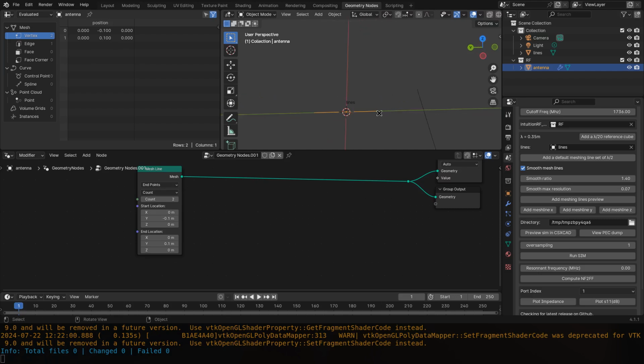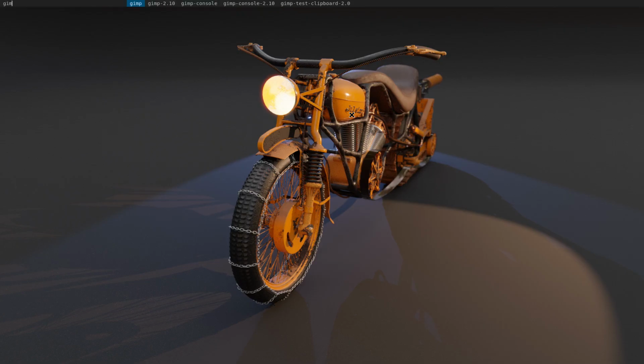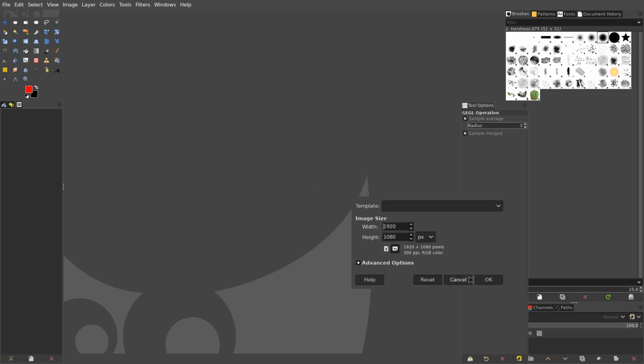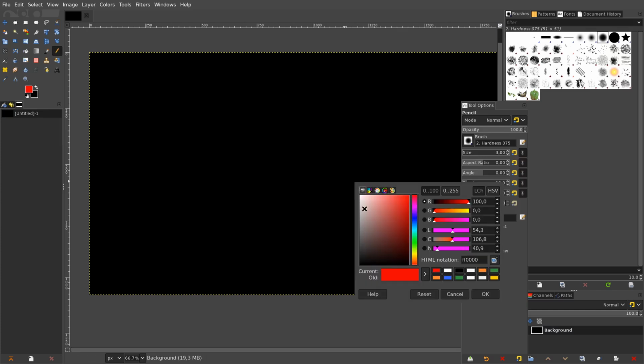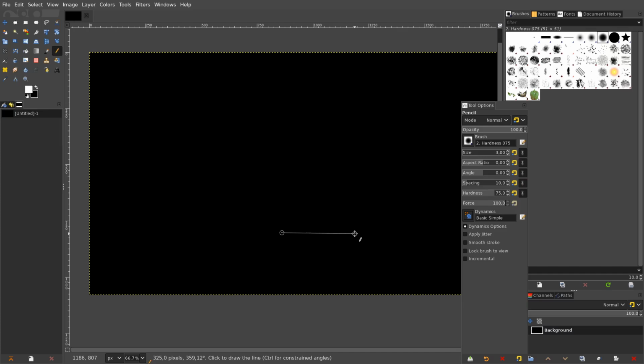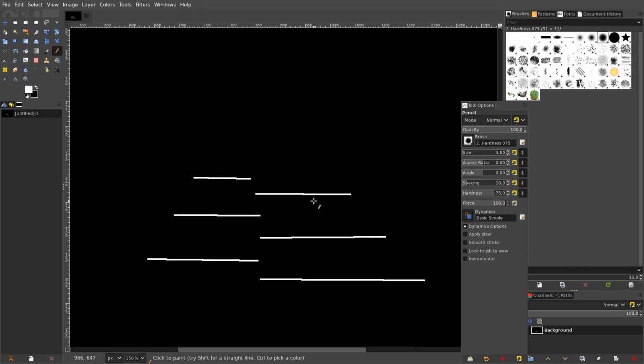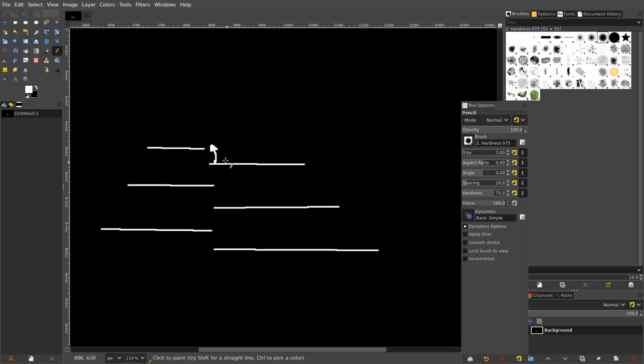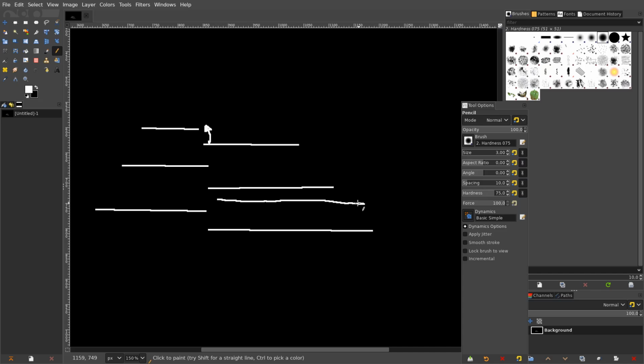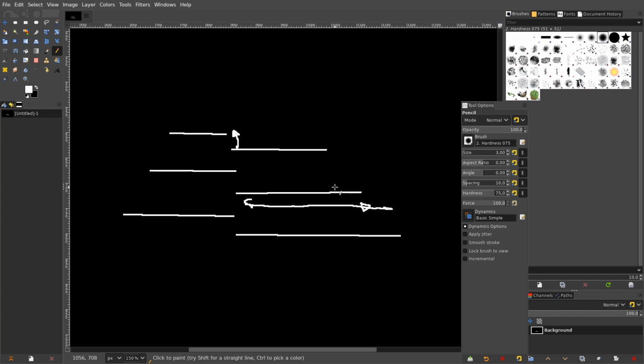Now what we are going to do is actually have a set of, let's call them, studs or monopoles or something, and have them every second one on a different side. So what you usually have in a periodic log antenna is something like this. You have an element here, and then a second element here, and then a second element here. Each time the gap here gets tighter, and the length here also diminishes from one element to the next. And it diminishes in a logarithmic way.